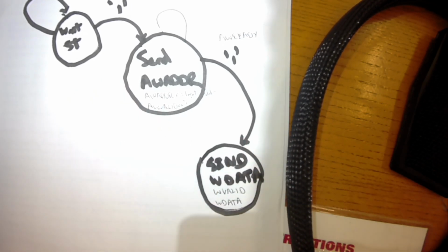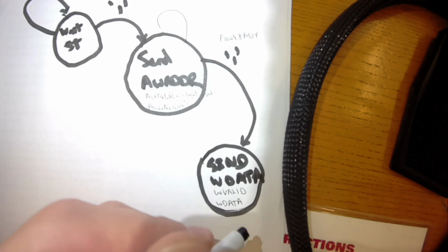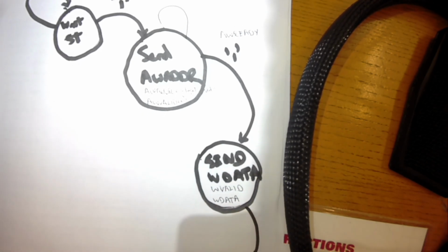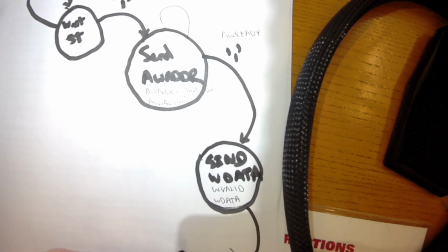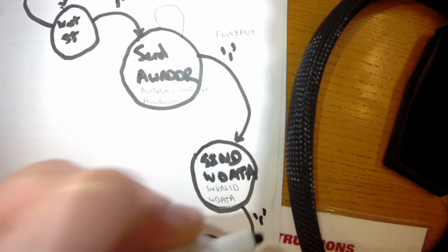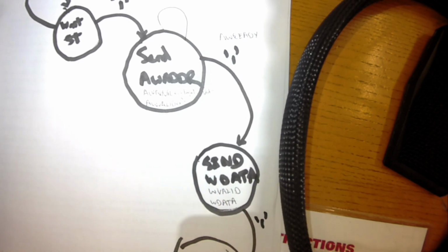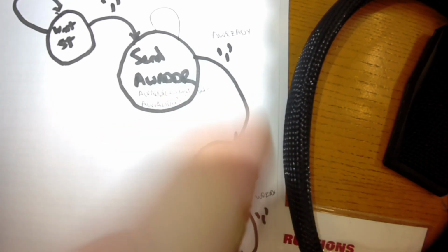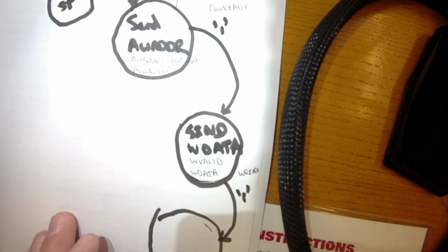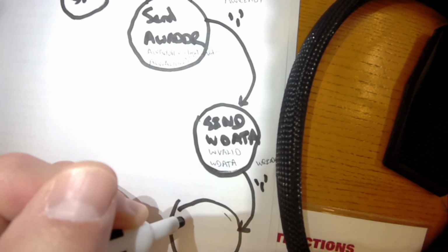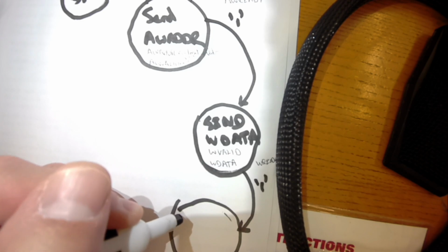When we get that ready signal back out, now if this is a burst transaction, we probably can do so without adding a wait state here, and that's perfectly valid. But when we get that ready back out, which is our now W ready signal, that the data has actually been read, I would probably do something like, just to get it to work, and then I worry about trying to overlap my updating and my sending of data.